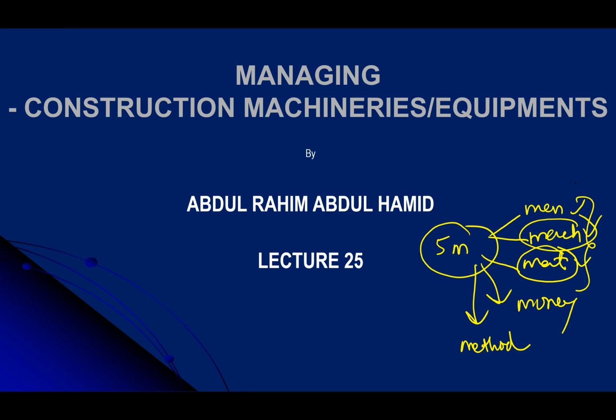So we already mentioned men last week. The video that you went through is basically about labor management. In that labor management, we already showed you how to do resource leveling and what we call resource smoothing technique. In computer software such as Microsoft Project and Primavera, the project leveling function is there, but the project smoothing function is not there, because project smoothing involves a lot of decisions by the scheduler, or basically the human itself. The machine cannot do that for the time being.